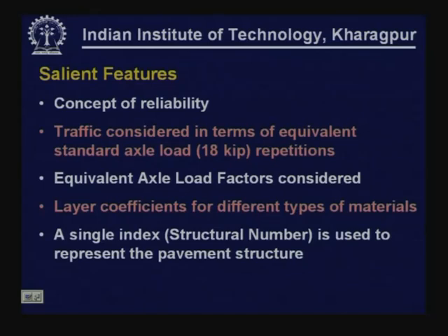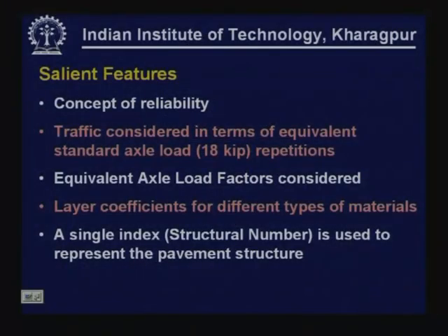Another concept that has evolved out of the AASHTO road test and has been used in AASHTO pavement design guidelines is the concept of layer coefficients to represent the contribution of individual layer materials, individual components towards the performance of the pavement. Stronger materials would give more contribution to better performance, accordingly they will have a higher layer coefficient. So, the materials are represented in terms of their layer coefficients and not in terms of the elastic modulus value